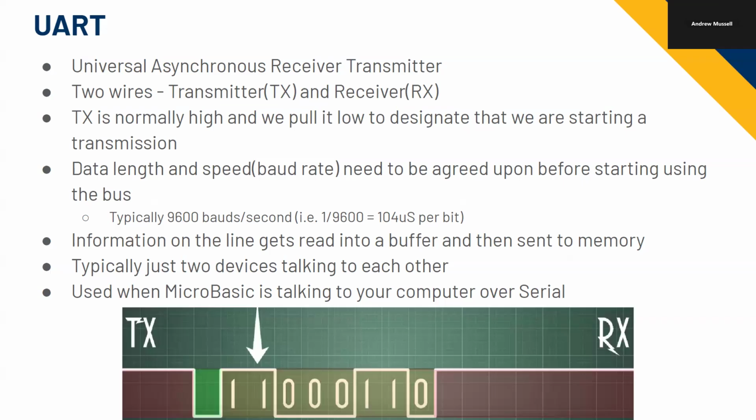Situations where you can change the baud rate, or do you just keep it at 9600 bits per second? The baud rate is something that you usually have to set up in the parameters of the bus, so you're typically not going to change that on the fly during communication. But if you didn't have enough bandwidth and weren't able to send enough data, you might want to change the settings of both devices to operate at a higher baud rate.